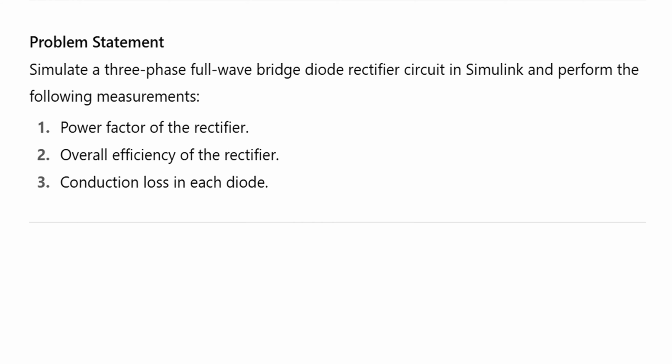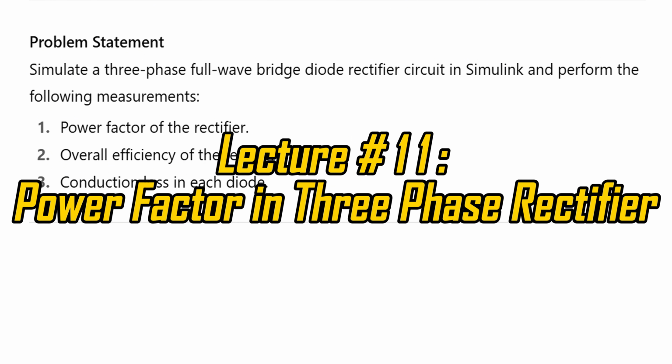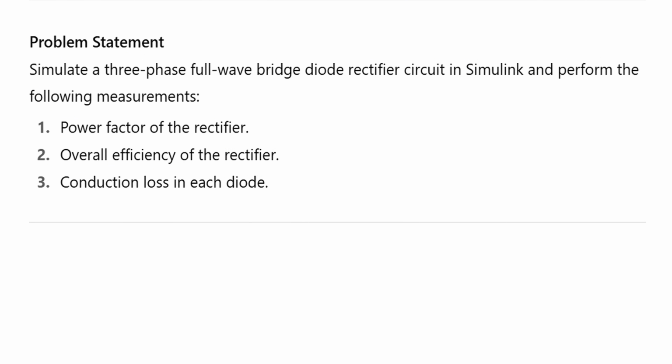In this tutorial, we will measure the power factor of a three-phase, full-wave bridge rectifier in Simulink MATLAB. Problem statement. Simulate a three-phase, full-wave bridge diode rectifier circuit and make the following measurements. 1. Power factor. 2. Efficiency of the rectifier. 3. Conduction loss of each diode.